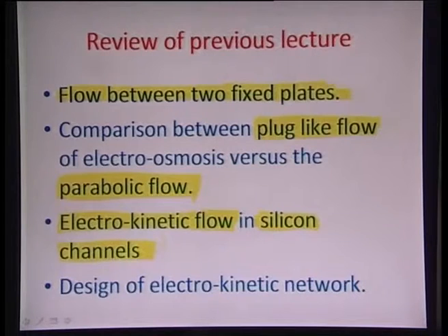Okay, and essentially a negative charge is developed on the silicon surface, and because of this, whenever there is water or any other constituent flowing within the microchannel, there is almost always this diffuse layer created in the bulk, and as it moves by an external voltage applied perpendicular to the cross section of the channel, it drives the fluid along with it